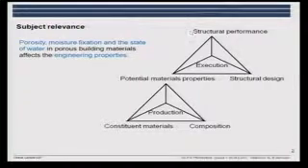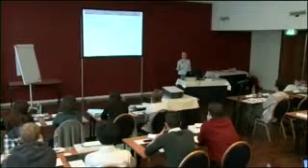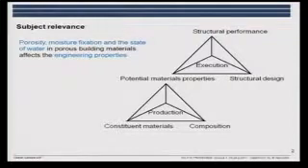Now it arrives, and we start to cast it. There's a structural design, the cover, that's the distance between the surface and the reinforcement, the configuration of the reinforcement. It could be other types of structural design issues, which has an impact on how the concrete actually ends up in the structure. So the execution, that's the casting and the curing. Concrete is like babies. We need to care about them during the time when they grow up, and depending on how we care about it, it will develop differently.